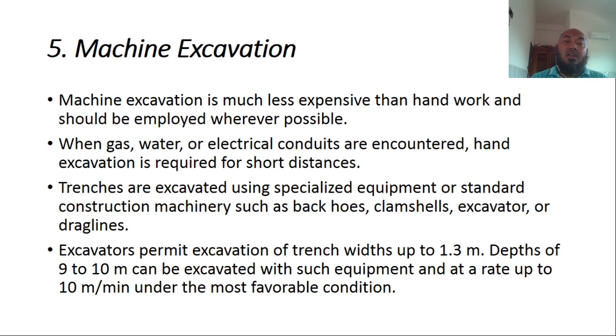Trenches are excavated using specialized equipment or standard construction machinery, for example, backhoe, clamshell excavator, or trenching machine. Excavators permit excavation of trench up to 1.3 meters wide, and depths of 9 to 10 meters can be excavated with such equipment, at a rate up to 10 meters per minute under the most favorable conditions.